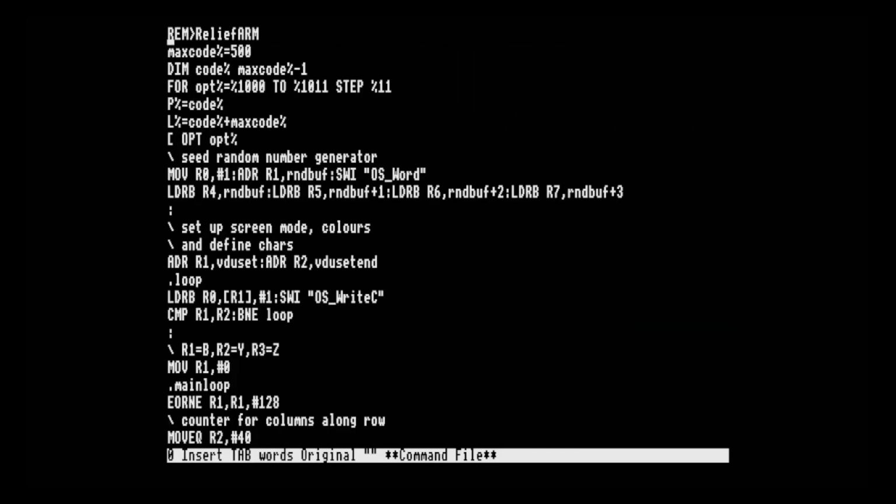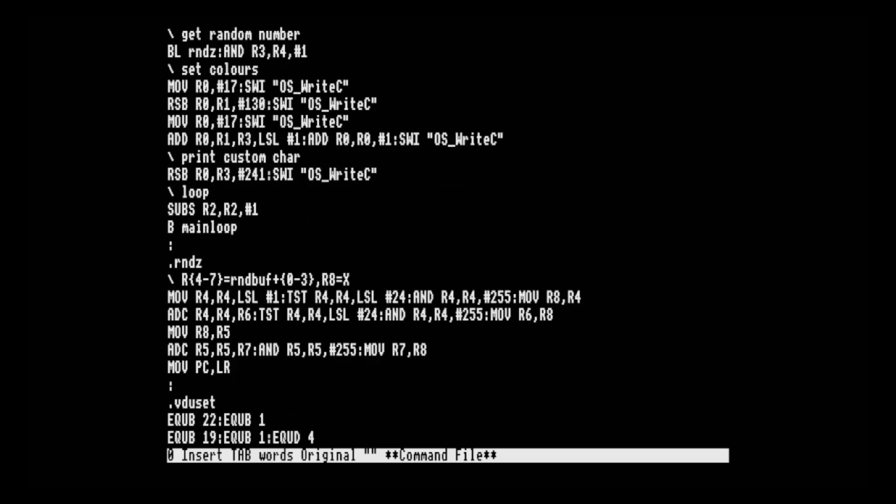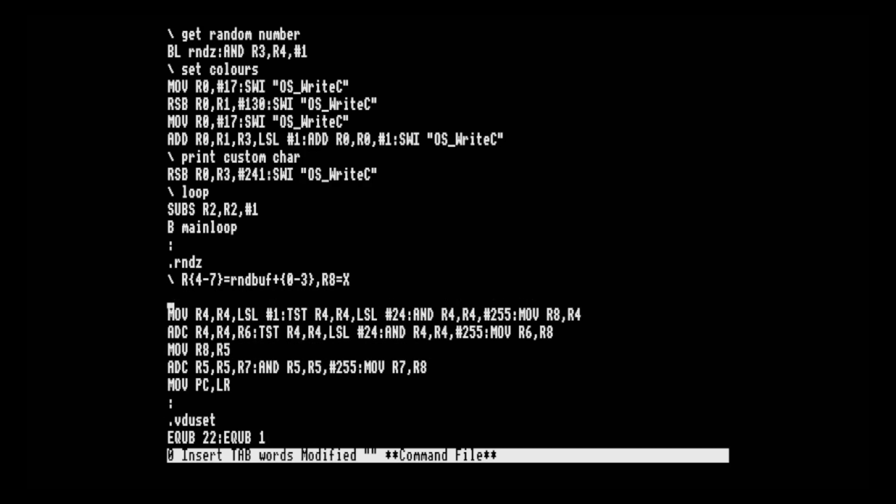That said, we haven't really improved things massively. I mean, we're still basically trying to run an 8-bit linear feedback shift register subroutine on a 32-bit processor, and we're doing a pretty nasty job at it as well. But what I was thinking was we don't actually care what this function does at all. What we really care is just that it yields random numbers.